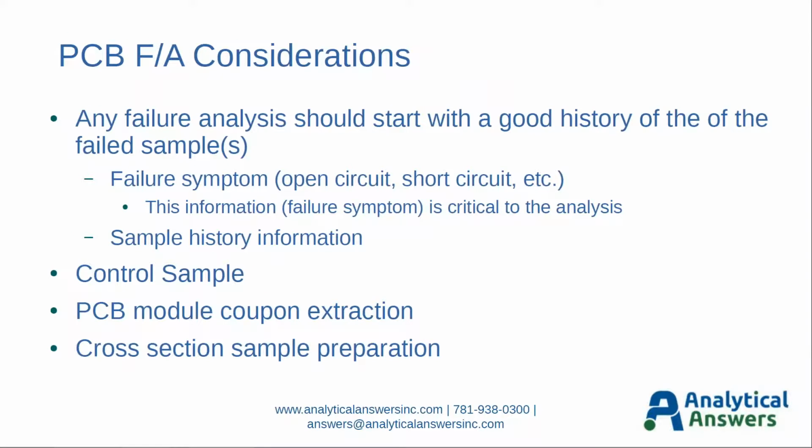So PCB FA considerations. Any failure analysis should start with a good history of the failed samples, and this should include what the failure symptom or symptoms are, whether it's an open circuit or short circuit, etc. This particular information is critical to the analysis. We want to be able to target the analysis to that failure symptom. We want to let the data speak for itself, obviously, but the failure symptom understanding is quite important here.